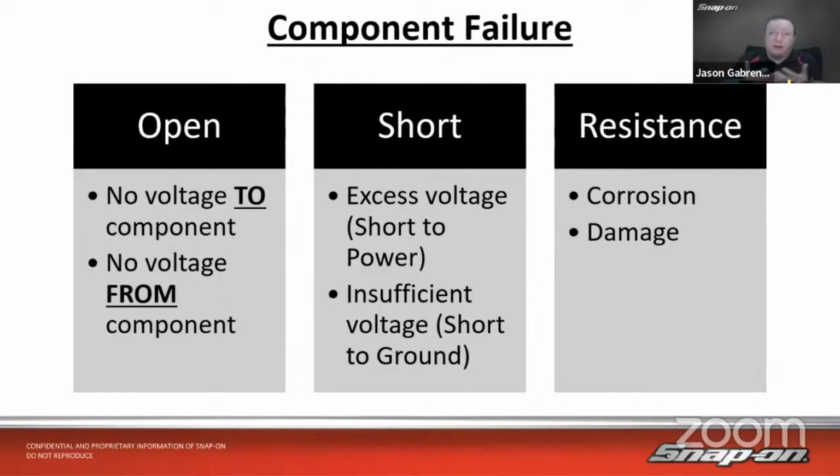I'm going to have continuity. Now, let's say I take one single tiny strand of that multi-stranded wire out and do the same thing, put my ohm meter on either side. Probably still going to get 0 ohms, no excessive resistance, continuity. But will that tiny little strand of copper wire start a car? Not going to be able to carry the amperage. It's going to get really hot if it tries, but that's a resistance issue. And you're really not going to be able to tell it with an ohm meter.